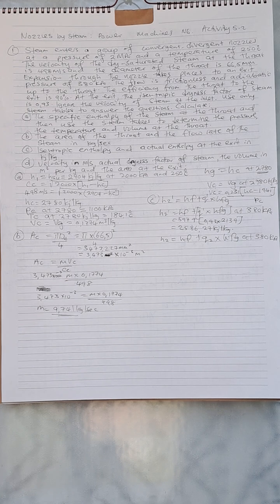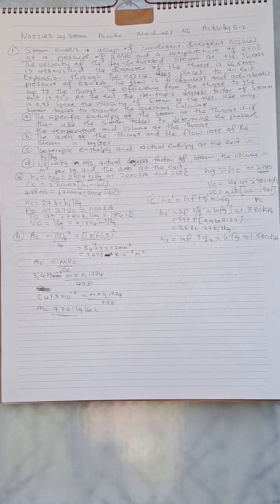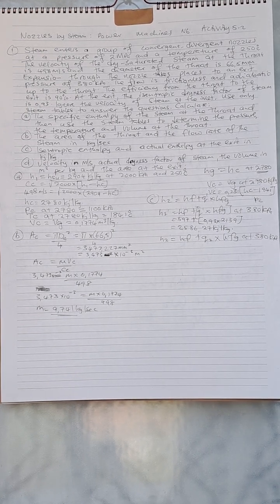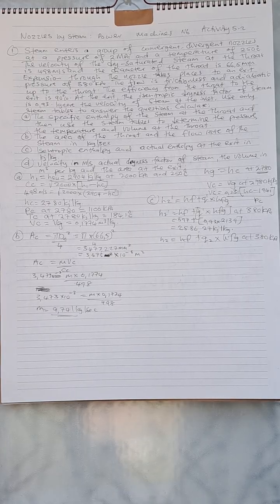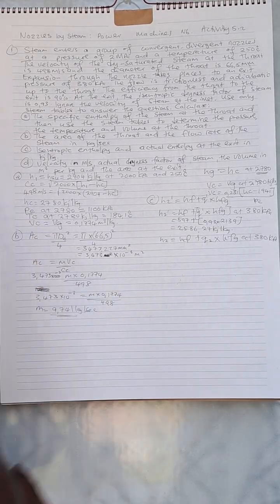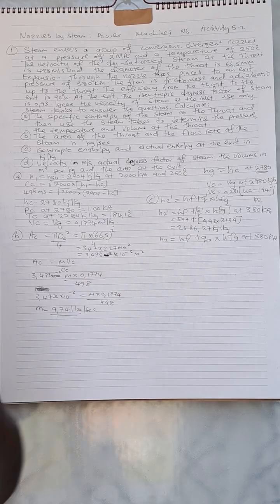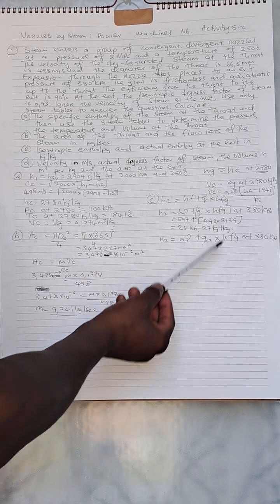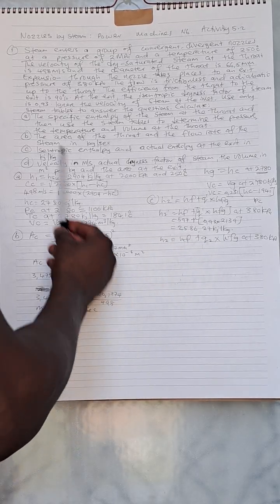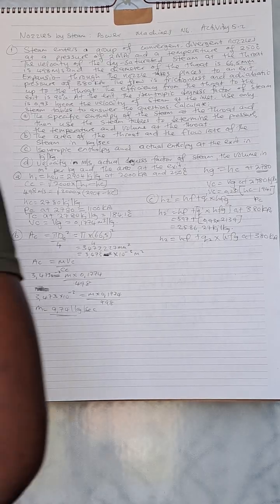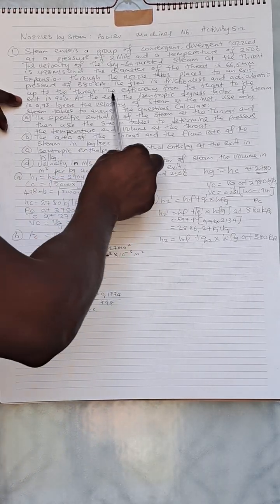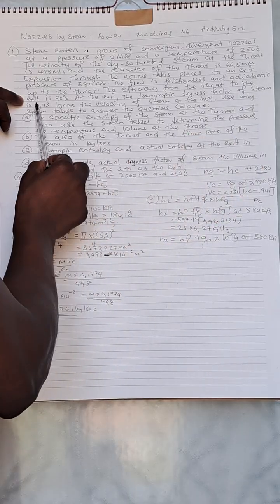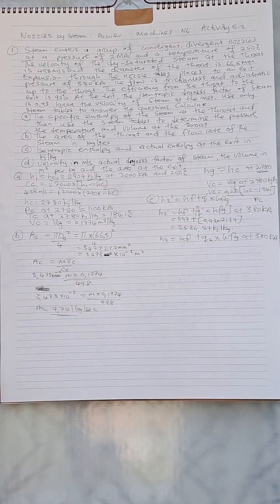So the conditions for getting our actual and the isentropic are the same because the pressure is still the same. But we just have one small problem. You can see that the actual dryness factor was not given, but we were given the efficiency from the throat to the exit as 90%.